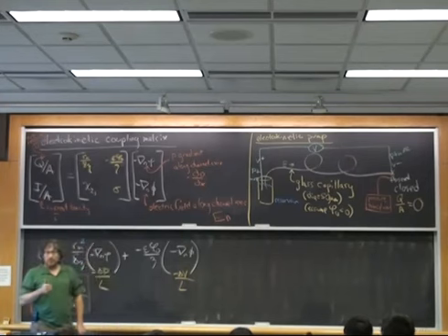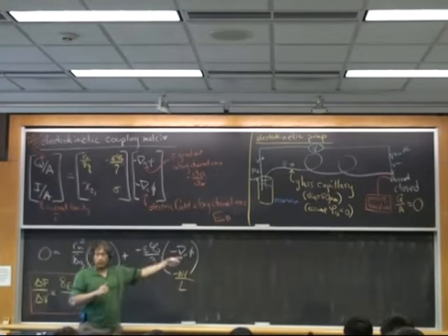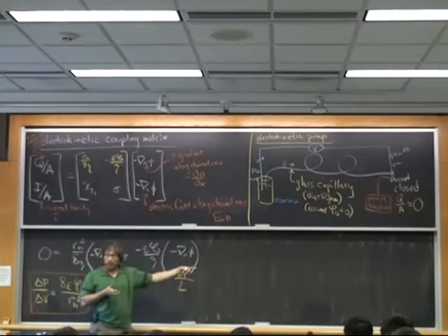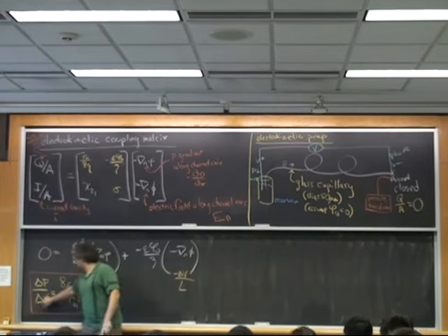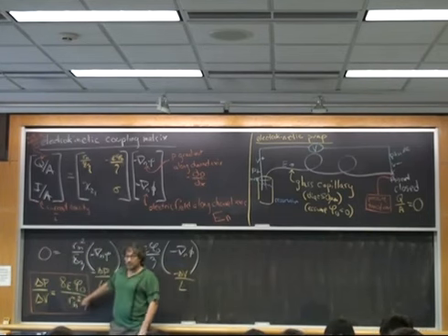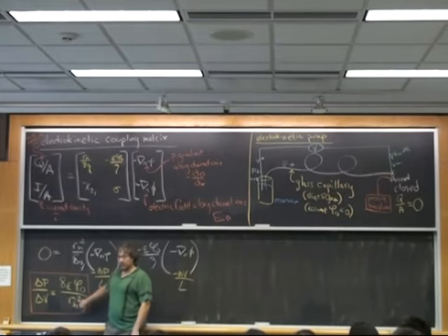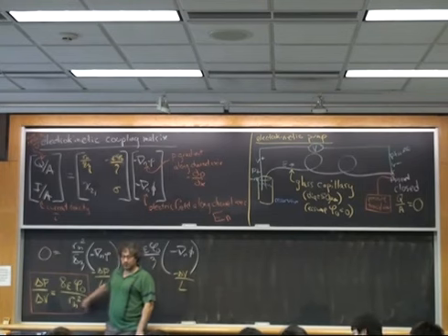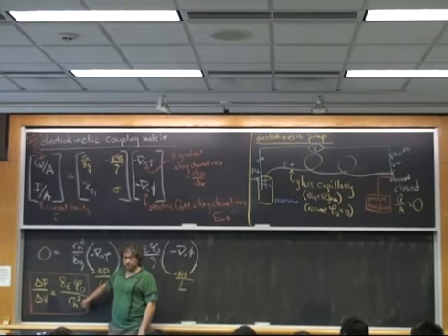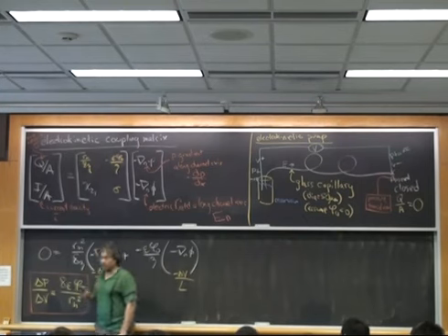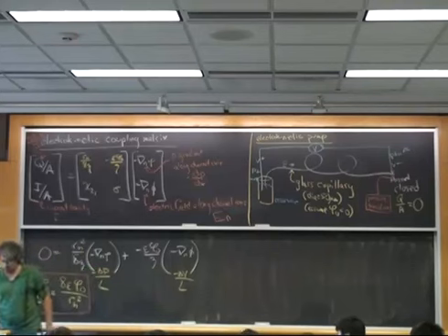It goes down. Whereas when I run it forwards, I can crank this pressure up really, really high. All I have to do is make my voltage high and make my radius low, and I can generate a really, really high pressure. I try to run it in the other direction. I run it a little while, and then the fluid cavitates. There's no way for me to generate a large negative pressure in this system. In theory, one can make a large negative pressure with water, but in practice, it's very difficult to do.